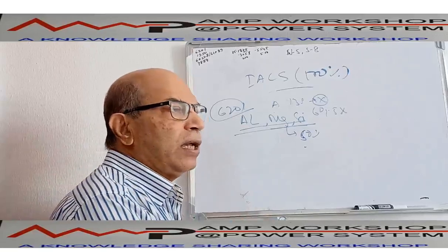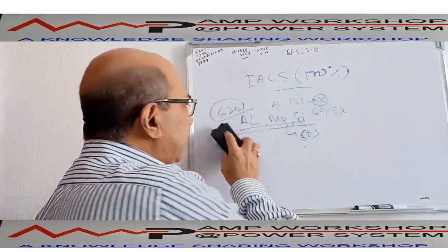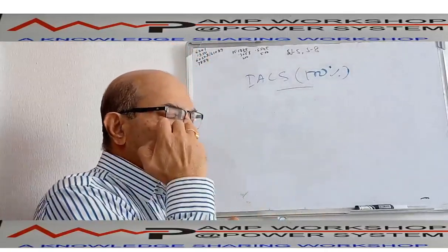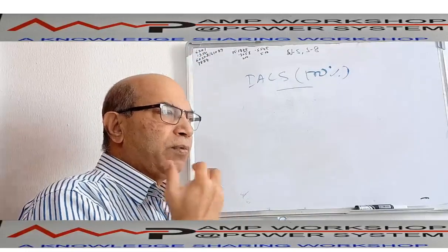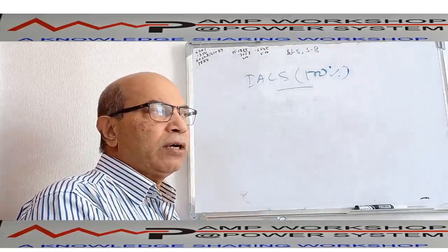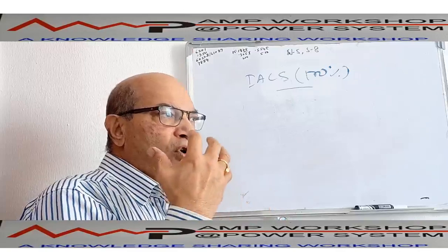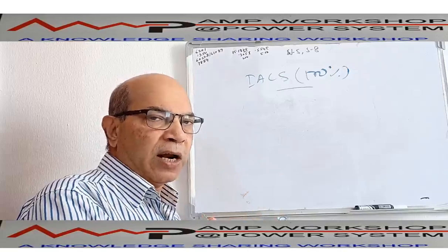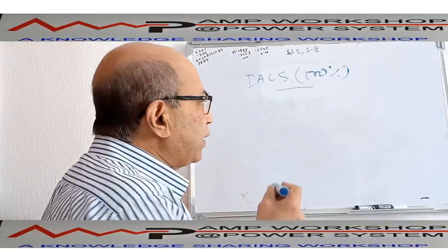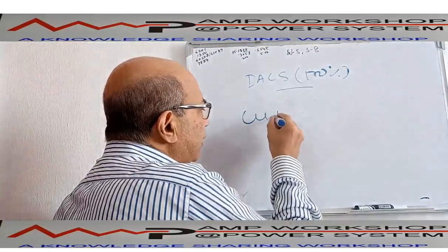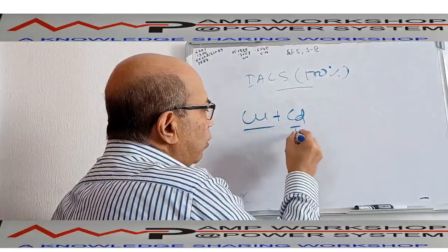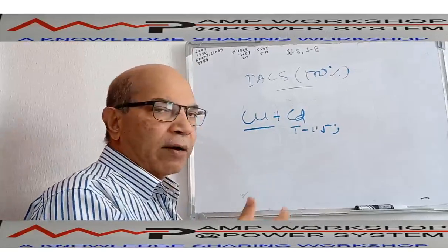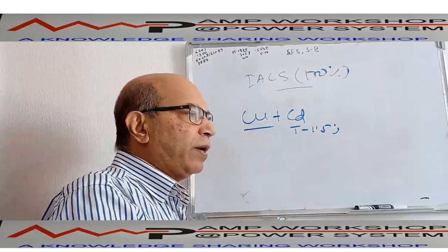That is also used sometimes in the conductor. And the third conducting material which we use is called cadmium copper. Now the point is copper mechanical strength. If we want copper to be used in a very corroded or polluted area, a pollution resistant material is needed. Copper is not very pollution resistant, but if copper is mixed with about 1 to 1.5% cadmium, it is called cadmium copper.